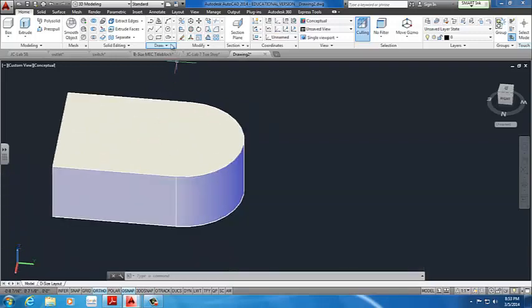Now the next step was actually creating that circle that we're going to cut out. So we can go to our circle command, and there will be a center point for this arc. I can't select it for some reason. An easy way, and usually it works, is if I just move next to the actual arc, it'll give me my center point. It's pretty cool, but at the same time, it's a hassle. But keep that in mind.